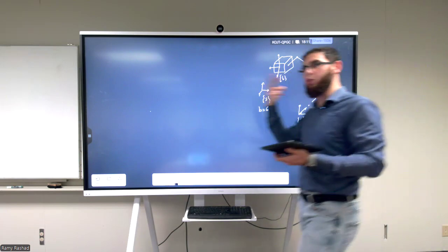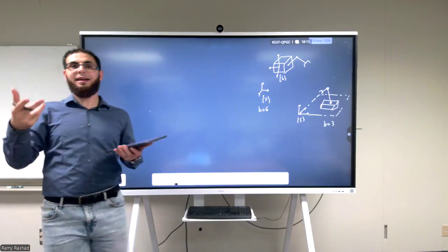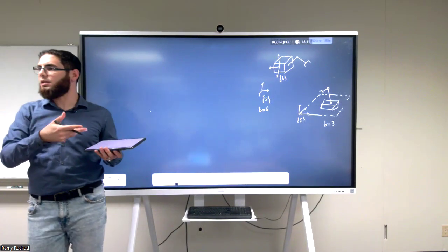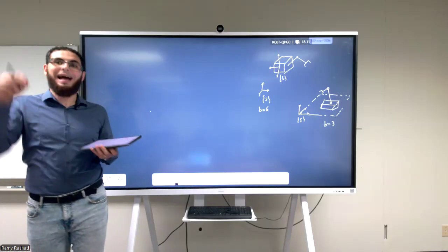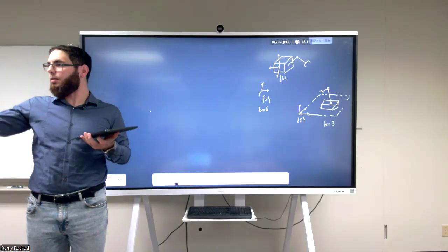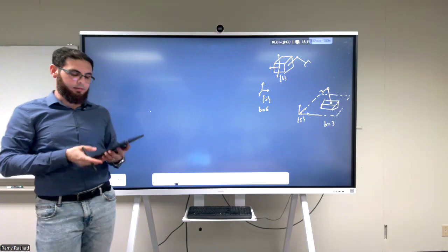By the way, this is also the same algorithmically, and numerically how it's implemented. For example, in the Robotics System Toolbox in MATLAB, when you want to simulate something like this, you need to add the floating joint between the base and the stationary frame.